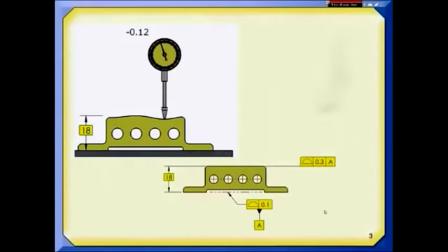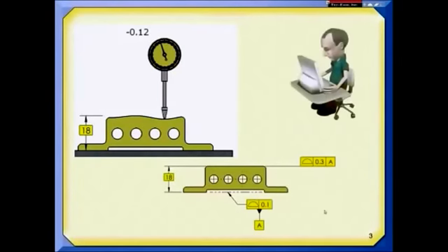In addition, though, engineering often wants a number that they can compare to the number stated on the drawing. Imagine that I close in on this surface with 2 parallel planes that remain centered at the basic location. I'm trying to squeeze these planes together to contain all of the surface. When I did that, I made contact with this lowest point, which was the greatest deviation.